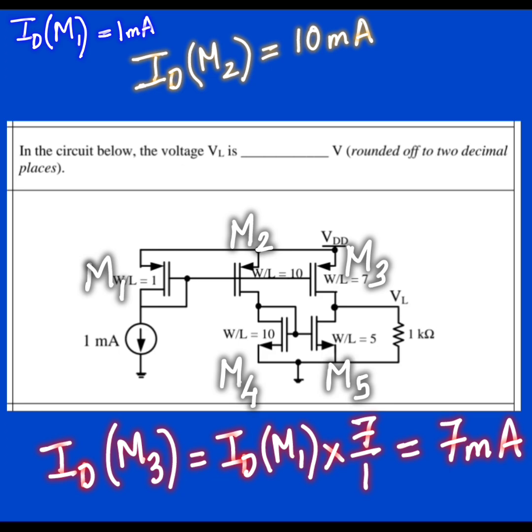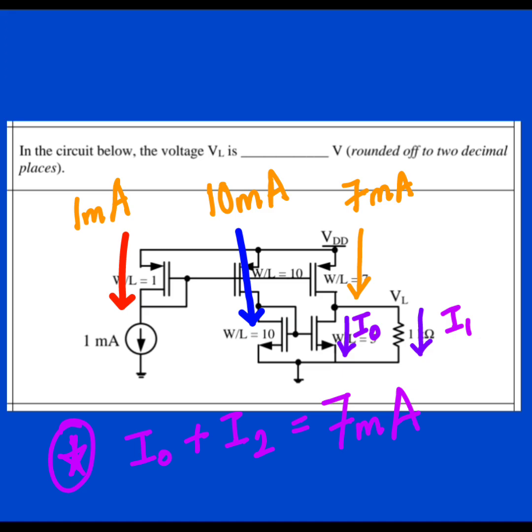Okay, so now from this M1, down there is another NMOS. Over there also the same 10 milliampere current is flowing. Here there is no dependency. Here it's a series connection, so the same current has to flow. So from this NMOS, where your W by L is 10, there also your 10 milliampere current is going to flow. But if you see in the right NMOS, I'm saying, there the